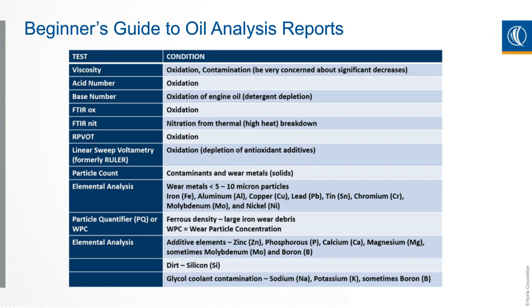Another test that's similar to that is the linear sweep voltammetry test. That's also looking for the depletion of antioxidant additives. So basically the remaining useful life of your fluid, your oil, overall oxidation levels. This is all very important.